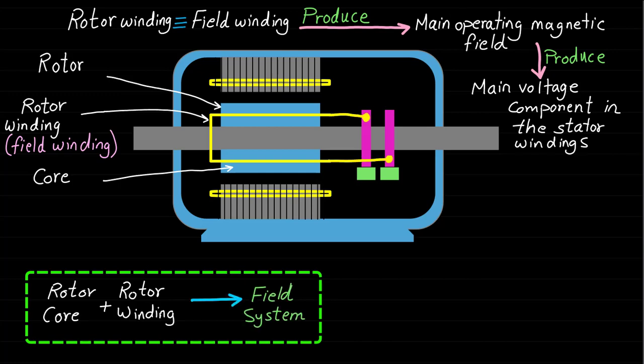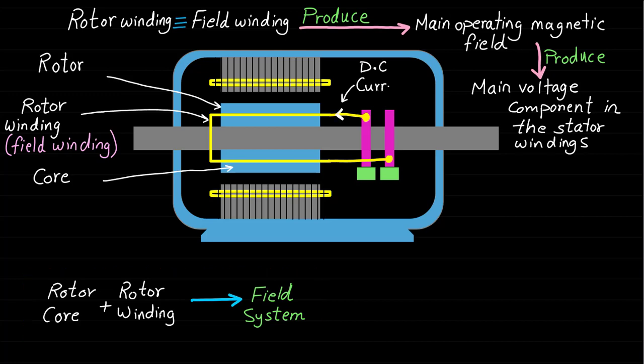The field winding or coil is fed by DC current. This DC current is fed through two carbon brushes B1 and B2 that slip on two rotating slip rings S1 and S2 as shown. The two slip rings are mounted on the rotor shaft and the brushes slip on them. The slip rings are metal rings completely encircling the machine shaft but insulated from the shaft.